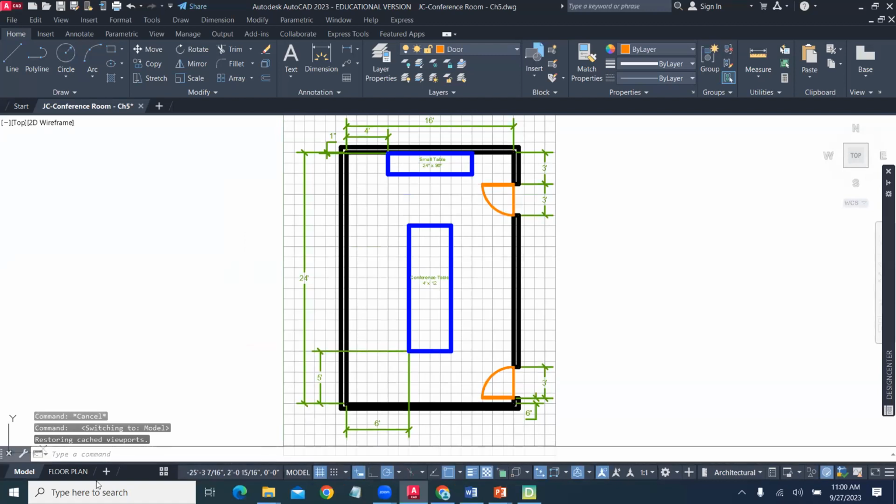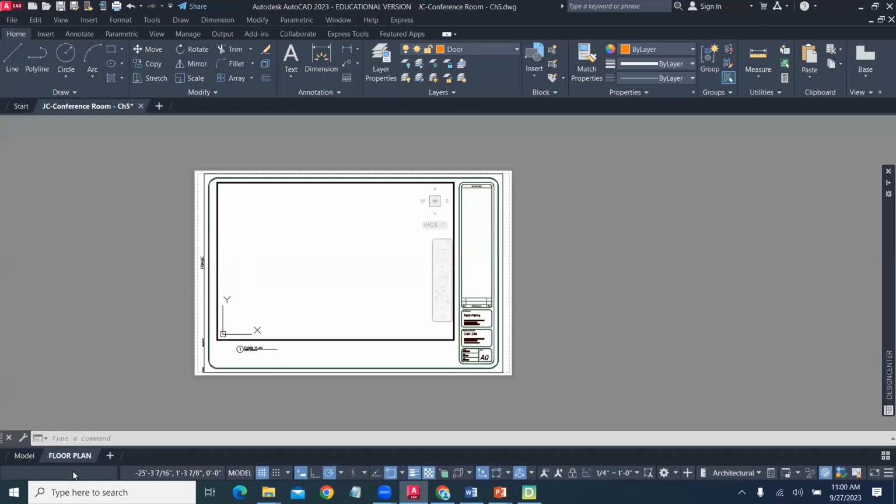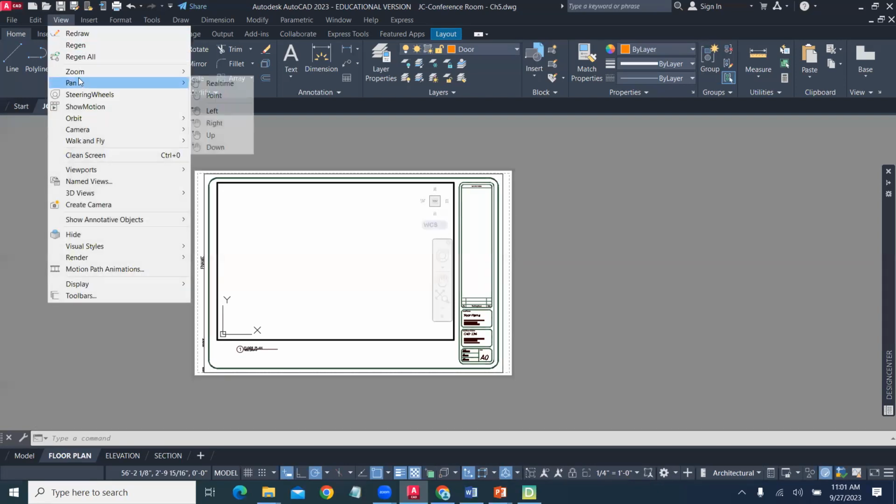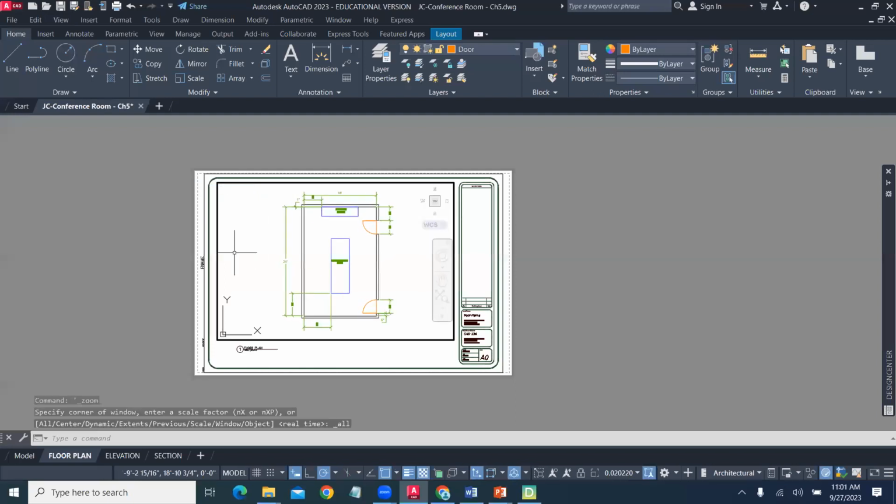And so when I switch over to paper space and I'm in a viewport, I'm in what's called floating model space. What I need to do is find my CAD geometry. You can either double click the middle wheel on the mouse, or you can go to View, Zoom, All, and that'll find your CAD geometry.